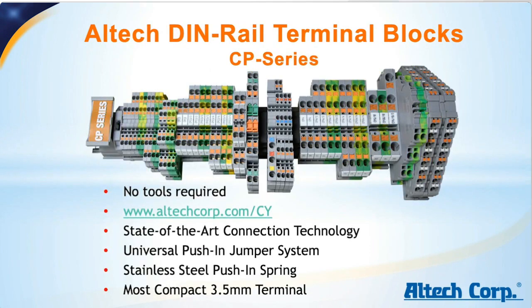Now the third and the latest series, that's the CP series, which covers the push-in technology. There's no tool required for wiring. Wires are just pushed into the terminal for a safe and secure connection. To release wires, this is done with a little orange push button on top of the terminal block, which can be accessed with any kind of tool. And besides the universal jumper system, the series features all the main terminal block types we discussed before.